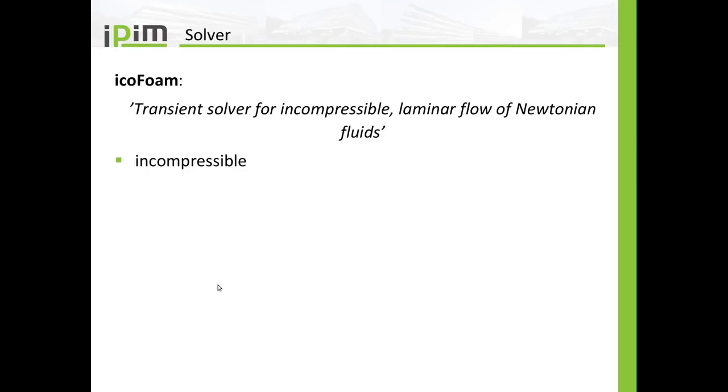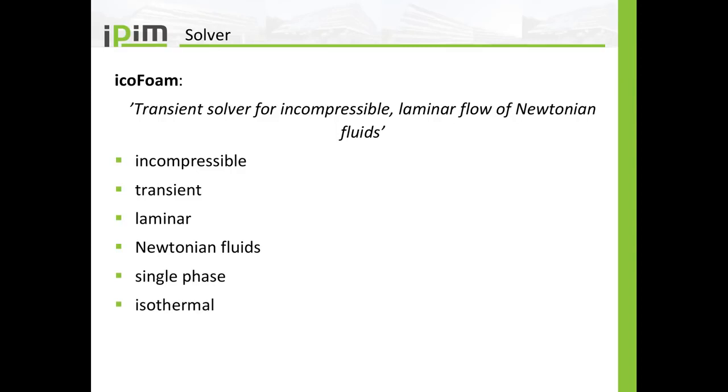For that, we will use the icoFoam solver in OpenFOAM. The official description is that it is a transient solver for incompressible laminar flow of Newtonian fluids. So this means that this solver is incompressible. It is a transient solver. It only works for laminar flows and only for Newtonian fluids. It is a single-phase solver and it is an isothermal solver.